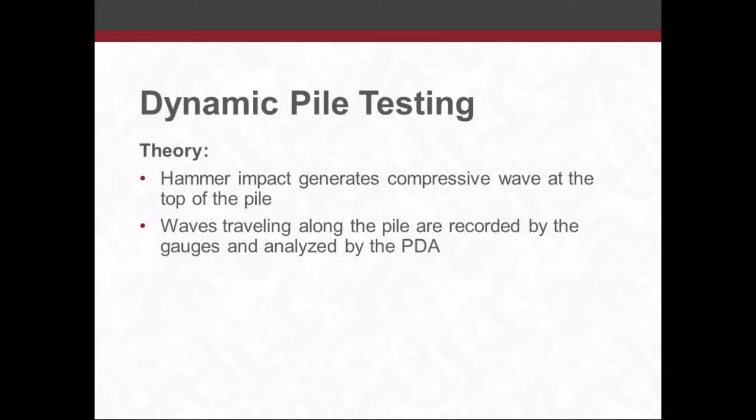However, when it gets to the tip, it can't move. So that generates a compressive wave, which goes back up the pile. And when that happens, that doubles the force at the toe. Driving into rock, driving into hard glacial till, it's always important to monitor the stresses at the toe of the pile.